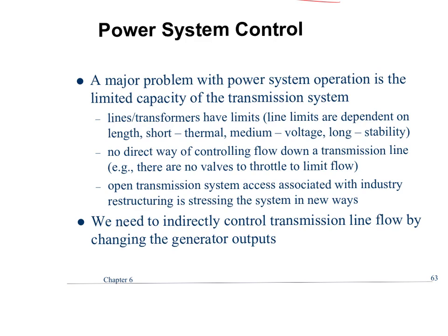So you're going to get a call from the utility saying, any way you're willing to shut down? Because they don't want to buy power at $900, because their costs are fixed, right? They can't sell it to the customer for more than the agreed upon price. So if the power goes up to $800 or $900, the utility is going to have to eat that. So if they can get the big company to shut off some load, it's going to save them from buying power at an exorbitant rate. So that's the reason why they do it. It's not because of the frequency. It's just because all the generation at that point is very expensive. And if they can shed some load, you can reduce the costs.